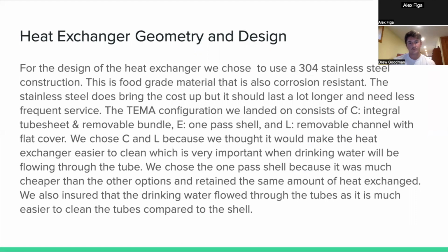So we decided to use a 304 stainless steel construction for the heat exchanger design. We chose this because it's a food grade material that's also corrosion resistant. This choice of material did bring the cost up a little bit, but it should last a lot longer and need less frequent service.